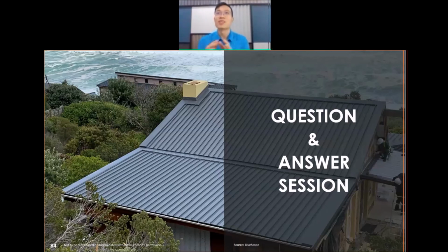To summarize that question, premature corrosion, how fast you will see it depends on the environment and on the material you use, how durable it is. So how should you prevent it? As I mentioned just now, have a wash down to dilute the salt particles. And if, at the early stage of design, perhaps you can also introduce what you call a non-reactive barrier to limit the exposure of vulnerable components from unwashed areas.